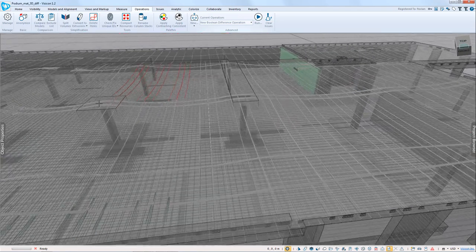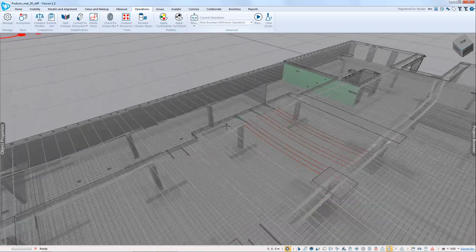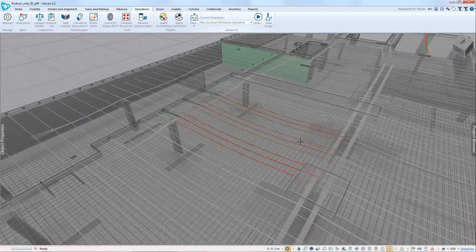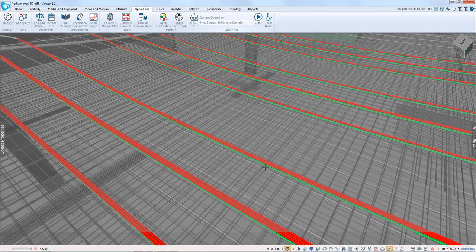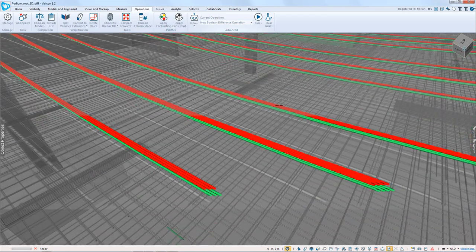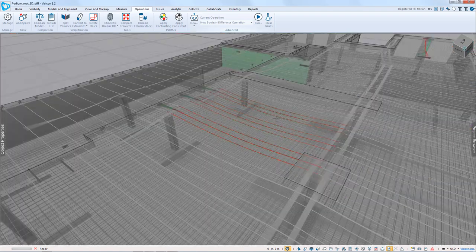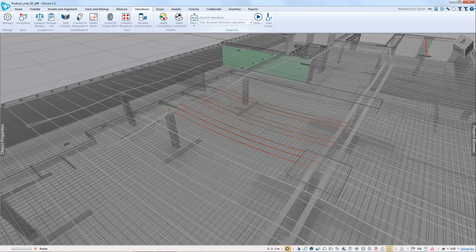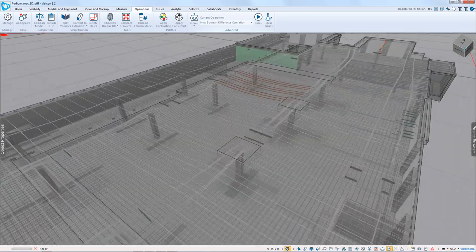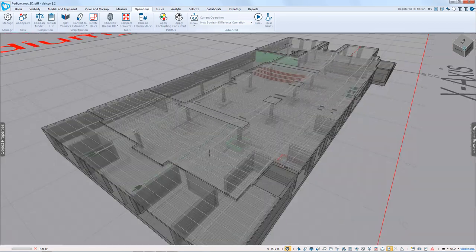I see some color here. We zoom in, and if we look in, we can see that that tendon, the drape, was actually moved from up to bottom. So again, these are subtle changes in the model that might go undetected, but I can use the 3D Boolean test to clearly identify where those changes are.